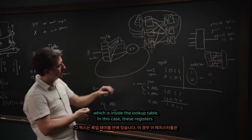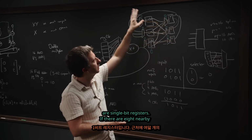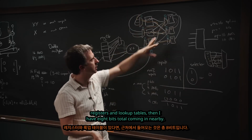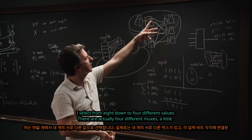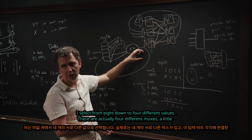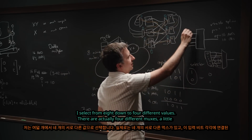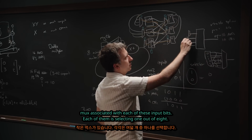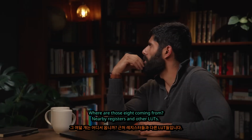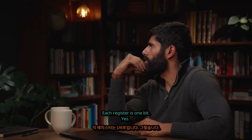So actually, I would say in this case, these registers are single bit registers. If there are 8 nearby registers and lookup tables, then I have 8 bits total coming in nearby. I select from 8 down to 4 different values. So there's actually like 4 different muxes, one associated with each of these input bits. Each of them is selecting 1 out of 8. And where are those 8 coming from? Nearby registers and other LUTs. And each register is 1 bit.